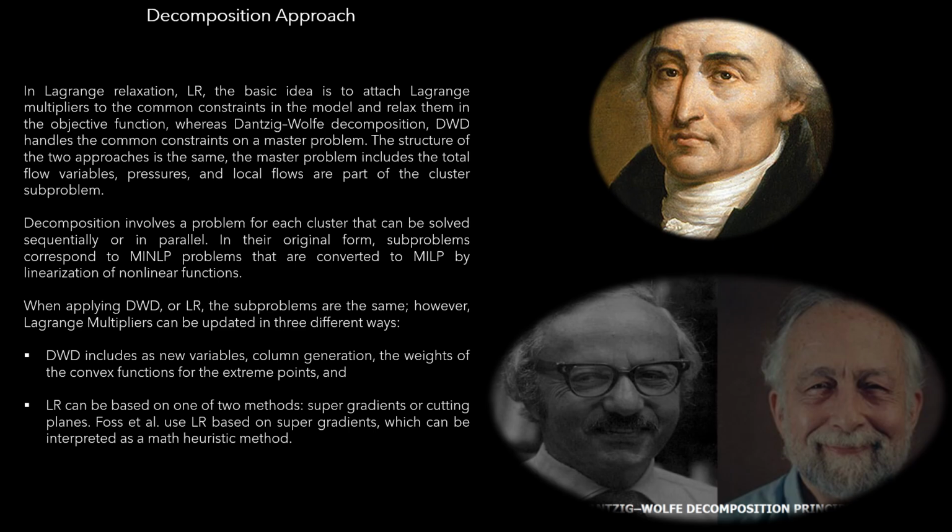In their original form, subproblems correspond to MINLP problems that are converted to MILP by linearization of nonlinear functions. When applying DWD or LR, the subproblems are the same. However, Lagrange multipliers can be updated in different ways. DWD includes as new variables, column generation, the weights of the convex functions for the extreme points, and LR can be based on one of two methods, supergradients or cutting planes. Foss et al. use LR based on supergradients, which can be interpreted as a math heuristic method.